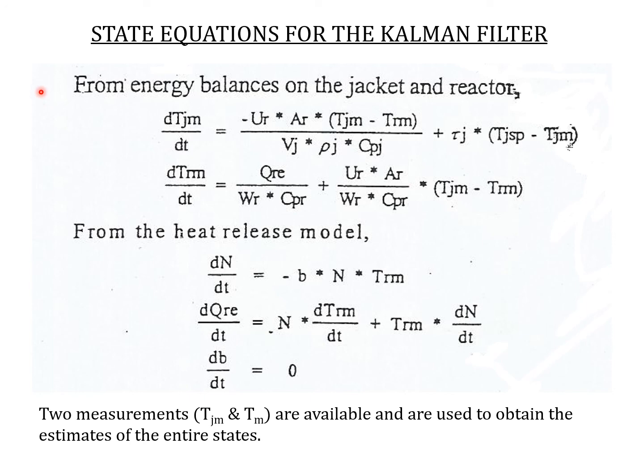So mainly this is for the case where we are estimating QR to implement into the GMC, because the main purpose is to get the manipulated variable U, which we mentioned as TJM, but in the real world is the TJ set point that is used to get TJM to follow that TJ set point.